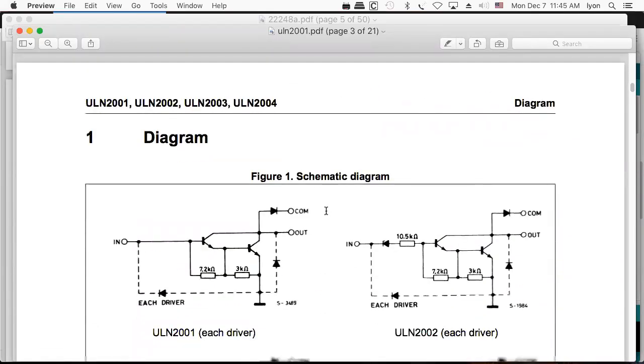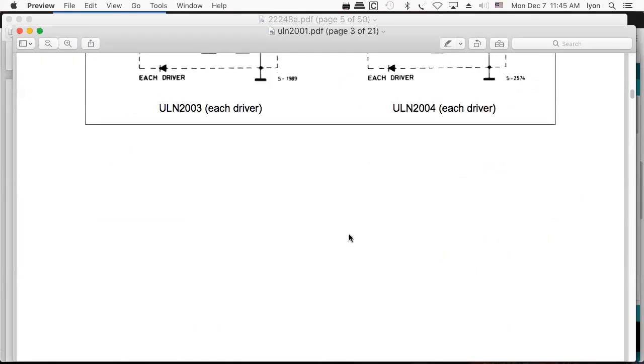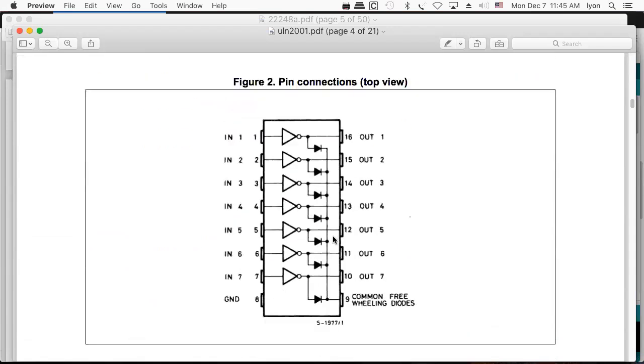And if you needed an ampere out of an Arduino, put in these Darlington transistor drivers and that'll give it to you. You'll take an input like this and it will allow you to float the driver voltage. And so that's cool. Here's the pinout. So now you can see why you can stack one on top of the other.